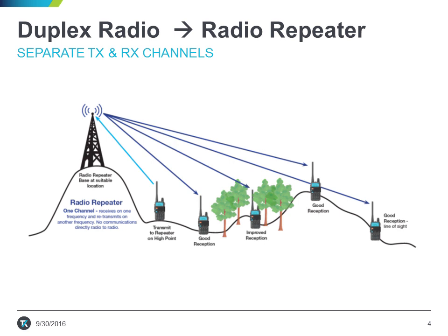In order to alleviate the problems with simplex radio, repeaters were invented. With the radio repeater, the radio horizon is now based on the repeater system itself. So those mobiles in the further ranges can effectively have further coverage provided by the repeater itself. The repeater, in essence, simultaneously retransmits all the information that's on the input channel to the output channel.